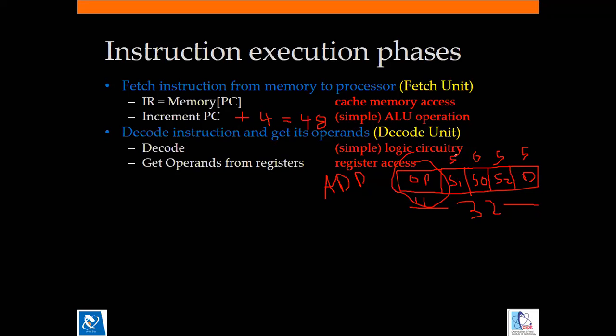Once it is found which operation is to be performed, the processor works out which registers to use as input. S1 and S2 both provide register numbers, one is input 1 and the other is input 2.